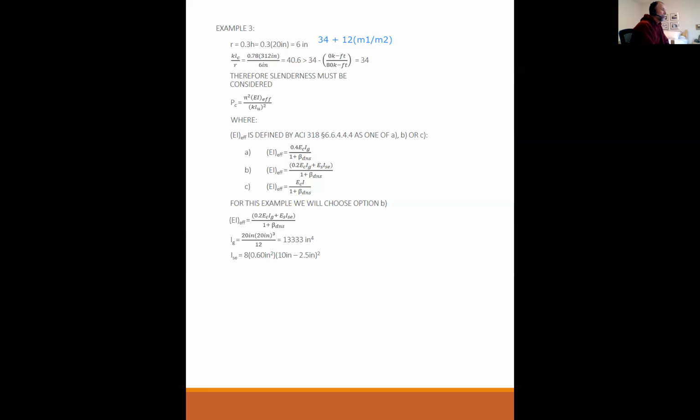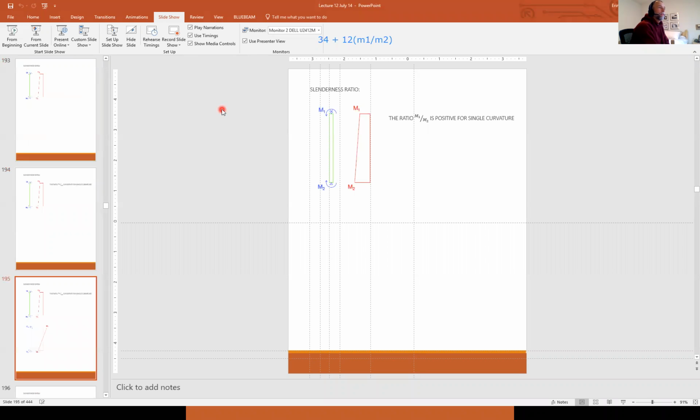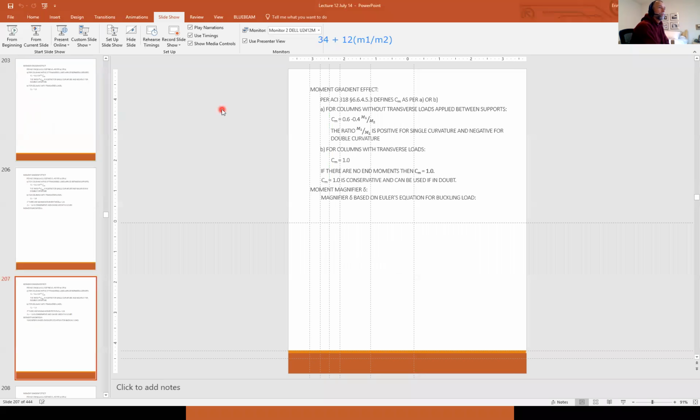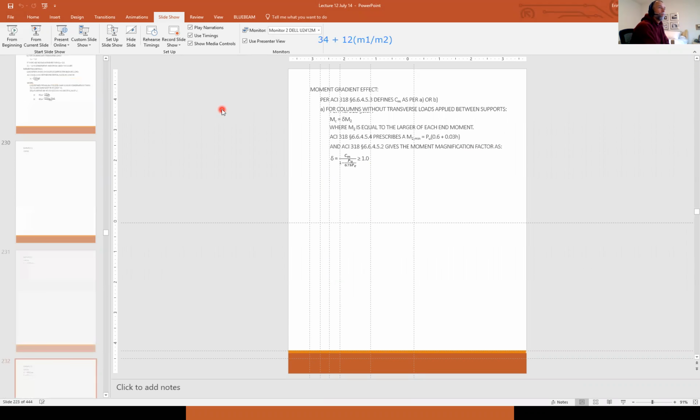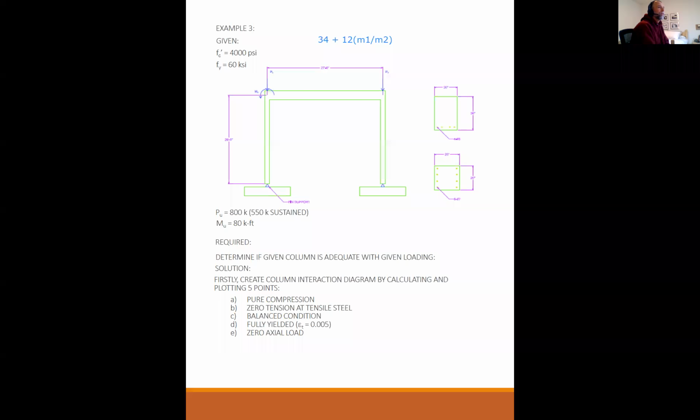let's see if I go back to, keep going back to this, but in our example, right there, and right there. Okay, so you see how all 4 bars are lined up on both sides? So from the center of the column, all 8 rebars have the same distance from the center to the center of the bar. So all 8 of them have the same effective distribution.